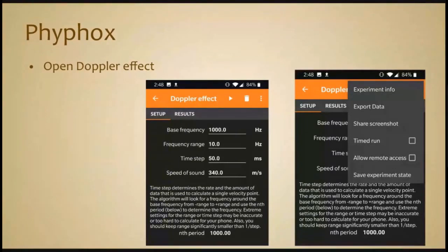That frequency range that you see, this 10 hertz, it is basically low pass up to what? So that means it will allow everything below 10 hertz to pass, and above 10 hertz gets blocked. So that means the output will be only 1 or 2 hertz. And of course, you have to multiply with the correct scaling factor and all. So this is how we detect small difference in frequency.